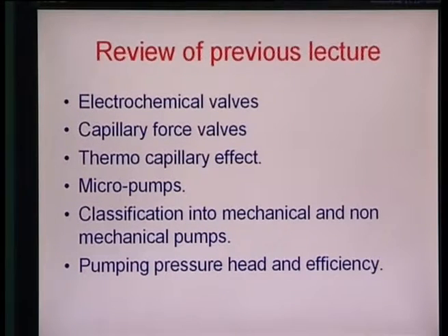and valving later on. As you know, capillary force valves are essentially based on electrical fields applied to bubbles with an unequal or non-homogeneous distribution of charge on the surface. Similarly, thermocapillary effect is done by changing the surface tension on both ends by heating a bubble differentially, and the idea is that the bubble moves towards the lower surface tension. Well, the surface energy balances for the bubble to move into that direction.